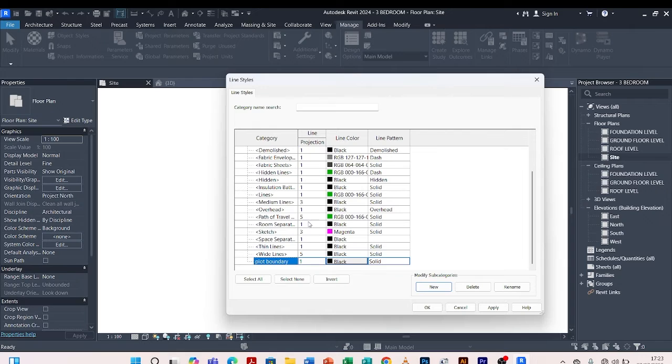So plot boundary. Then this is the line weight, how thick you want it. That is mostly when you're printing your work. At least we have to see the line first. You have to make sure on your floor plans the things you have to see first. I must see the boundary first. So that means the line weight for our boundary wall has to be thicker. So that's what I will have to see first. For this case, I can give it 8.